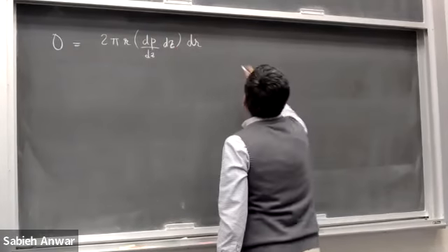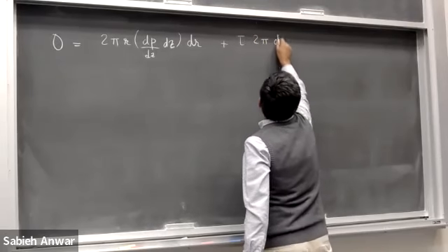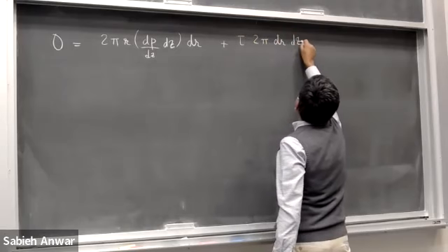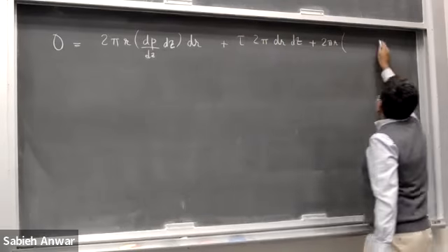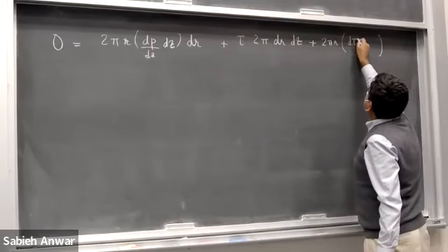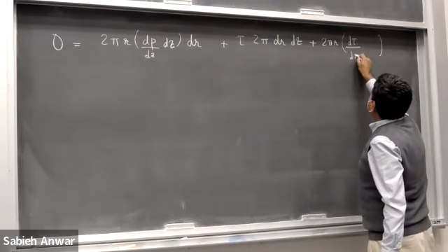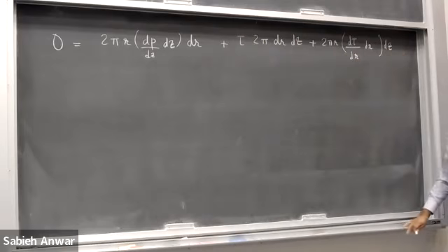So then I move on to plus tau 2 pi dr dz plus 2 pi r. Now instead of d tau, I would like to write how does the shear stress change with the radius? And then apply a chain rule again. The first order term in the Taylor expansion. And this is what I'm left with. You get this?